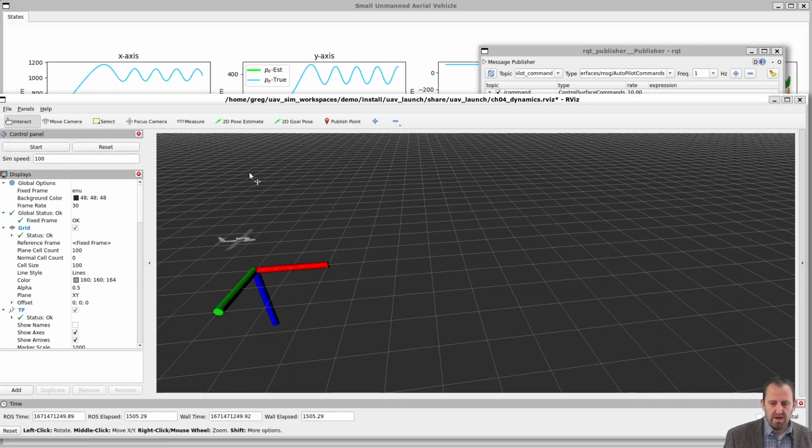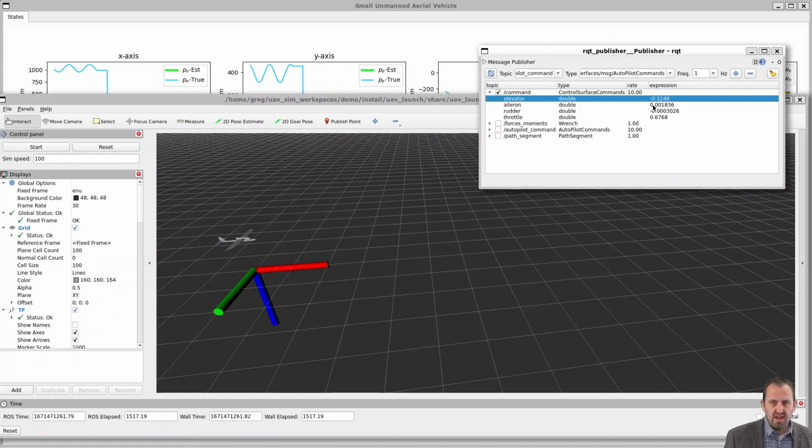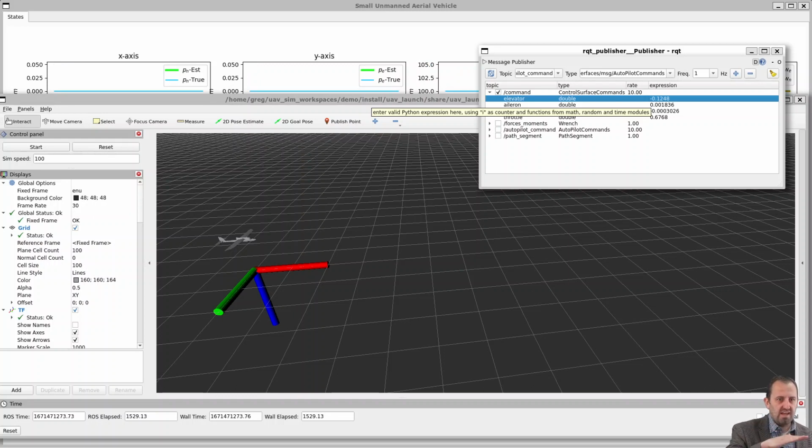So now going back to our control surface commands, let's take a look at what happens if we perturb each one of these just a little bit. One thing to notice is that these are all non-zero. For example, it requires the elevator to be negative, meaning it's trying to pitch up just a little bit, and that pitching up allows it to stay in level flight for that small amount of time we saw. To keep us in straight flight, we require just a tiny bit of rudder. We require our ailerons, and remember, our ailerons are for the rolling, because we have our motor going that's putting a moment about the IB axis that we want to overcome. So we have these non-zero values that keep us moving straight.